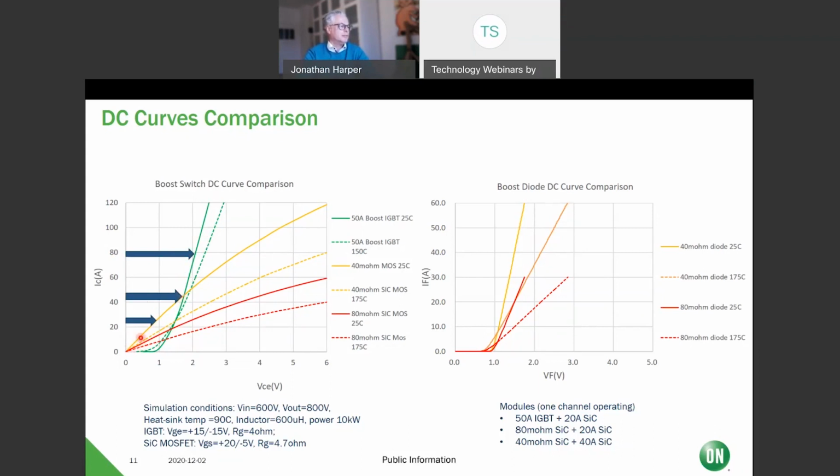So, conclusion: SiC MOSFETs have lower RDS(on) and lower losses in this area. Interestingly enough, they have a higher dynamic RDS(on), as you can see here. This has got a very good dynamic RDS(on), dynamic RCE, to be extremely precise. But the point is, with an IGBT, you've always got this 1 volt drop, caused by the bipolar effect, which gives you disadvantages.